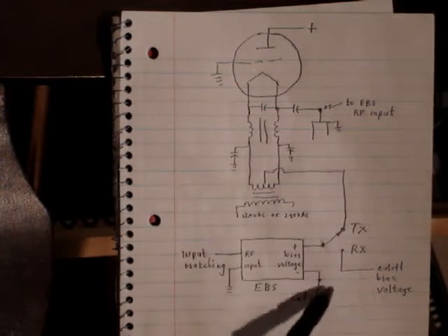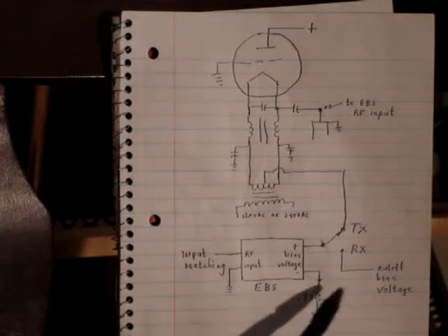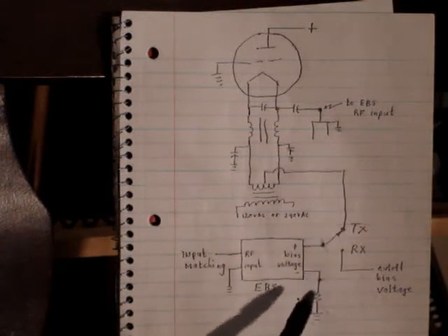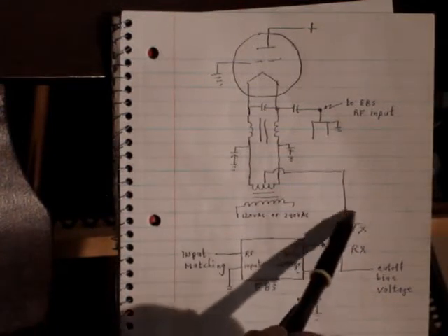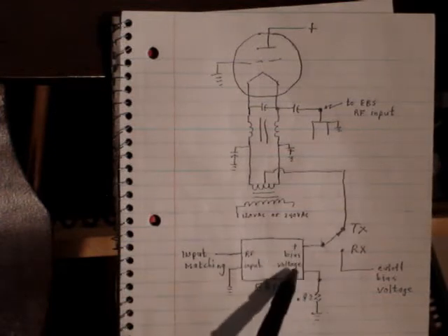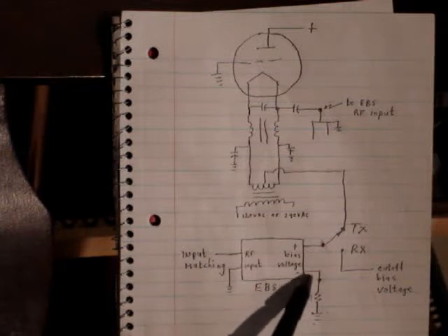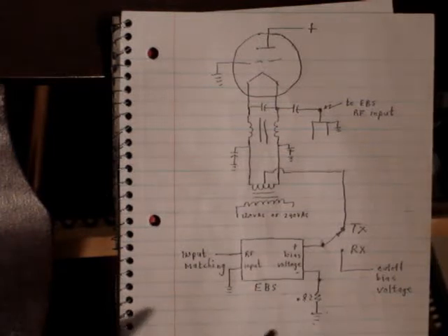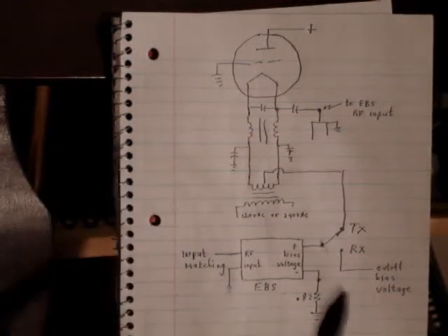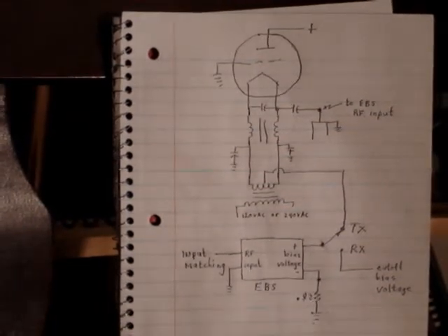You have to disable the other Zener diode or remove it out of the circuit. It's easier just to disable it by shorting across it. And then we'll show where we can open the, take one wire off, put the existing Zener wire go into here, and then we'll have to add a little jumper wire from this output to the previous wire that was there. So that's it. This is the only circuit that has to be unsoldered and a little wire replaced. This just has to tap into it.